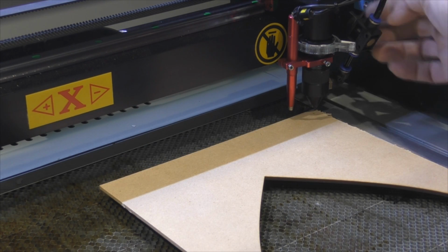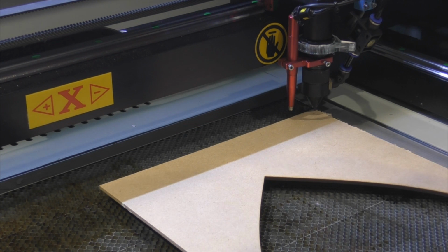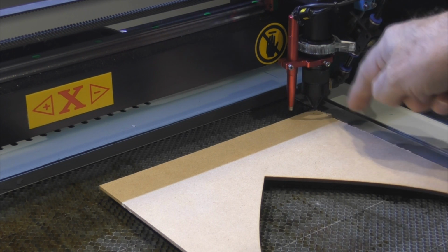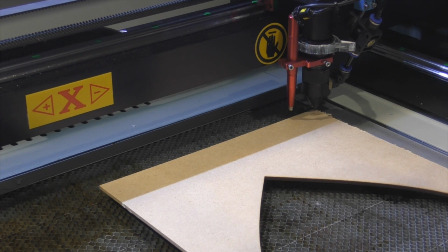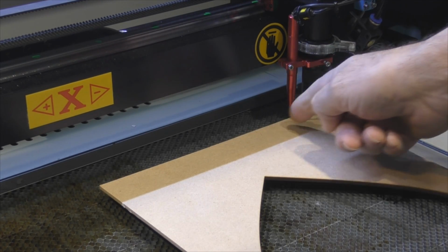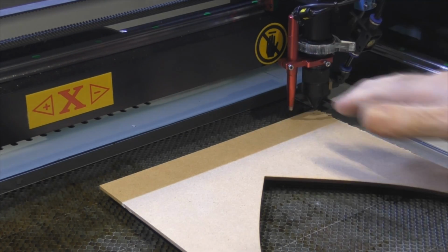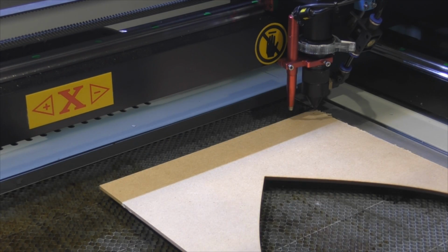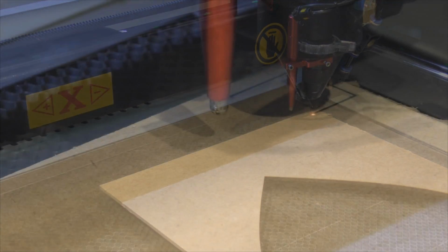The other thing that I want you to note is I have got this air assist fully open. It's most essential for all organic materials when you're cutting them to get the most efficient airflow you can through that very thin cut that you're going to produce. That is where the smoke is going to occur, and that is where you've got to get the smoke away from. You don't want any smoke basically coming back up onto this surface. If it comes back, it will get blown down again and it will produce a brown mark around the edge of your cut. So you'll know that your efficiency of blowing is not very good. So I'll now turn the extraction on.